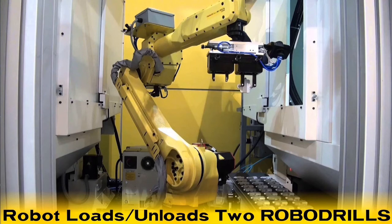Lastly, we have a robot that is unloading 2 drills from this machine. And so the best way to do this would probably be a continuous path, so not a controlled, but a continuous, to where the robot would be in the machine. You could grab a color that shows up a little bit better. So the robot would be in the machine. We might tell it come up here, out here, and then down here into this tray. And so point to point might work if there's not too many obstacles here. We might be able to have the robot do this basic motion.